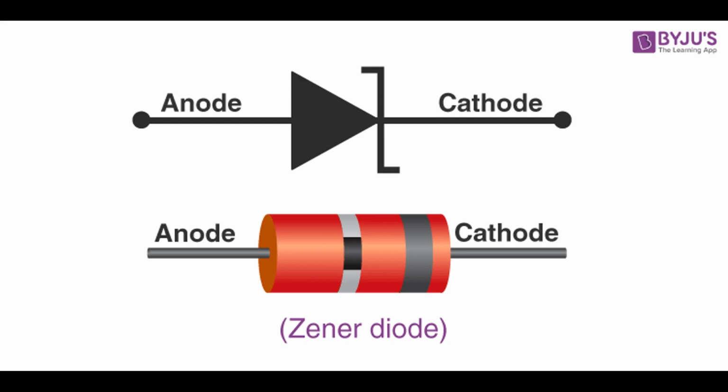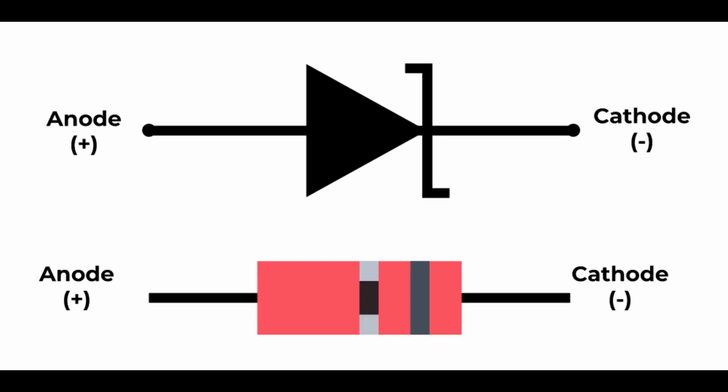Positive clamping: the diode clamps the waveform to a positive voltage level relative to the biasing voltage. Negative clamping: the diode clamps the waveform to a negative voltage level relative to the biasing voltage. Dual clamping: two diodes can be used to clamp both the upper and lower limits of the waveform.